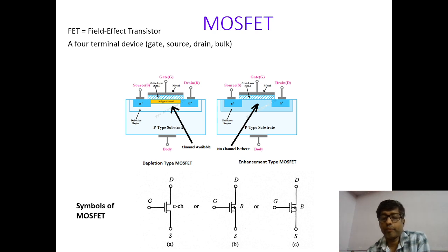So an increase of the negative gate voltage enhances the induced positive charges in the semiconductor. These positive charges are the p-type carriers confined to a thin region called the channel, below the oxide layer. If the positive voltage is applied to the source with respect to the drain, then the p-type carriers in the induced channel carry the current from the source to drain.